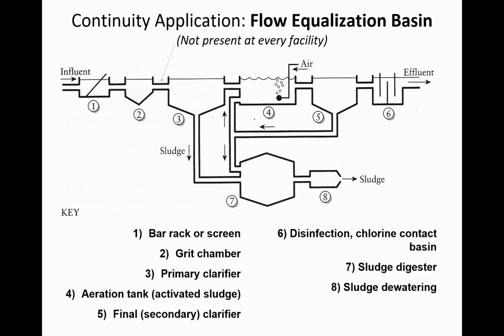It would cause a negative environmental impact, because sugar, although it's not poisonous to the environment, and although it's not going to harm any aquatic life directly, would deplete the oxygen in the river, because the bacteria that would be breaking down the sugar would also consume oxygen. And that turns out to be the number one effect that can have a really negative impact on an ecosystem, when there is a decrease in the dissolved oxygen that fish and other organisms use to live.